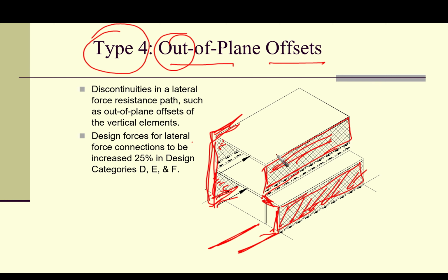So whenever we have story shear and it goes down to be transferred or transmitted from one story to another, there are some shear forces in this direction that are going to be transmitted through the floor itself, which is something that we do not want. We need to take care of this part, which is the connecting part between the two lateral resisting systems, the offset. So this means that we need to take this part into consideration.